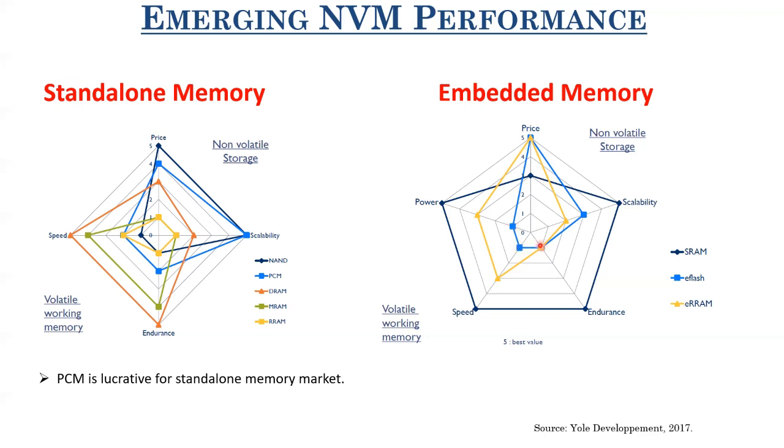Also, in terms of endurance, as I already told, these flash memory devices, because of the wearing of tunnel oxide, 10^5 cycles is almost the maximum that a single NOR flash device can give you in terms of cycles for which it operates correctly. So in terms of endurance, it's poor.